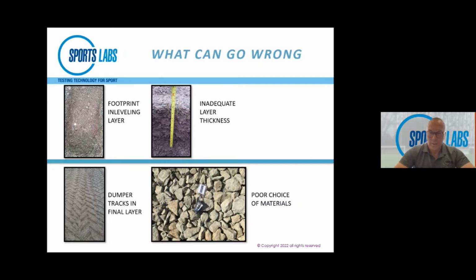And then we see inadequate thickness. So what's happened there is subgrade is very up and down, bumpy, or they've just put a thin layer of subbase. This is about 6 or 7 inches thick, which is, you know, in that scenario wasn't thick enough. Next slide, please.